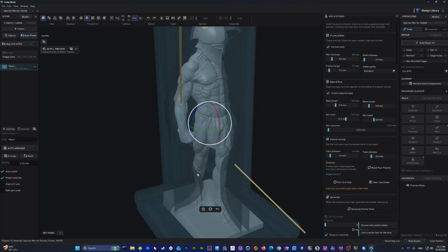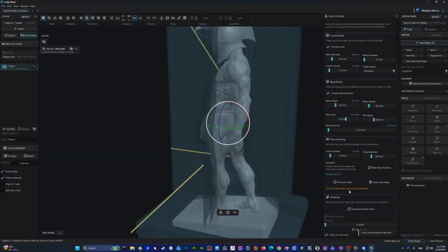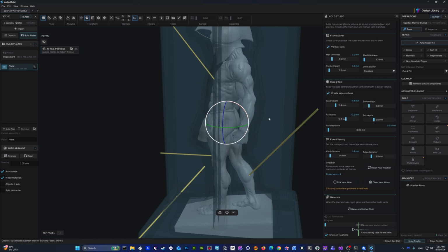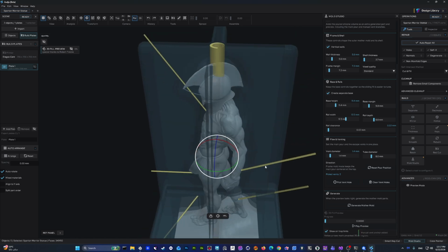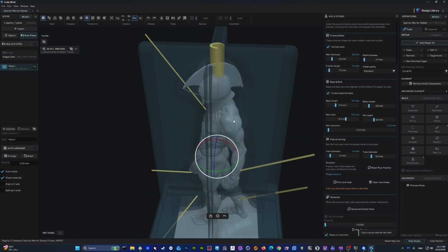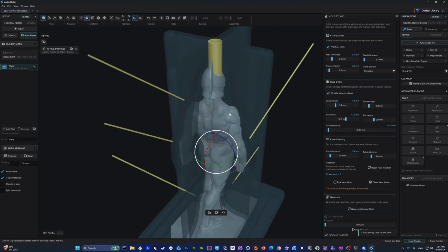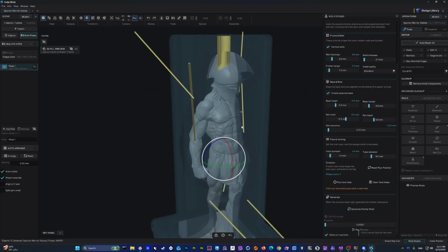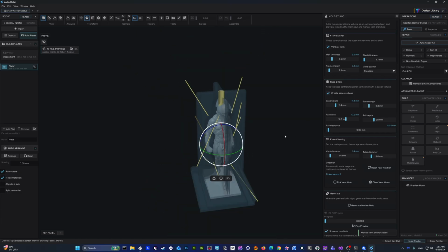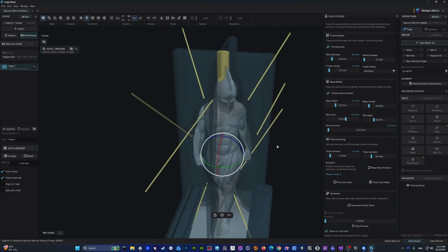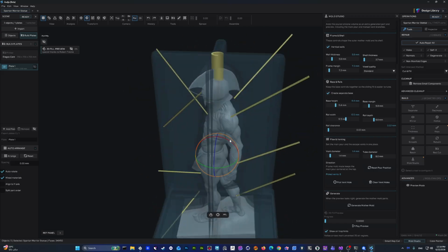Like you just put different vents in different places, so there is no air trapped. Maybe here. And this air trapped for the mold, so the silicone mold will not get air trapped, so it will not create bubbles or be destroyed. So for example, like this, maybe we can put something here. All right. This part will have holes.